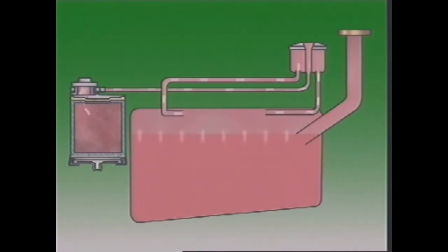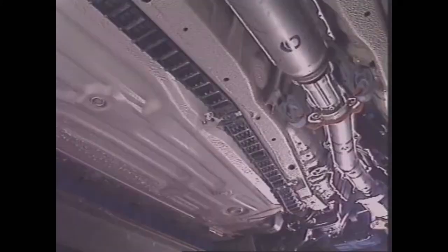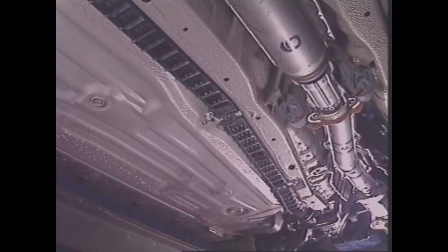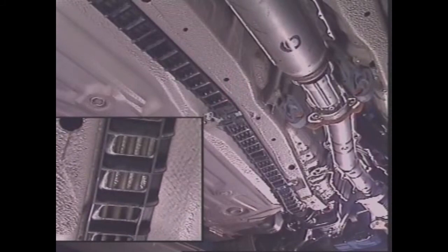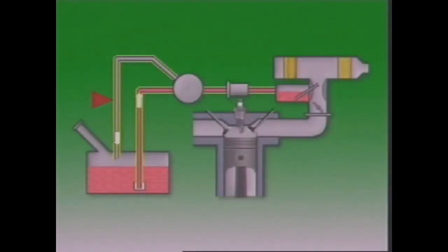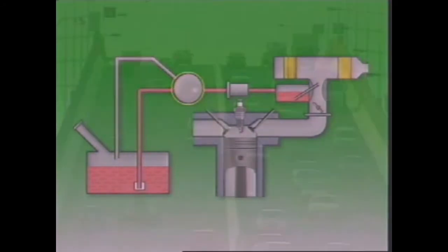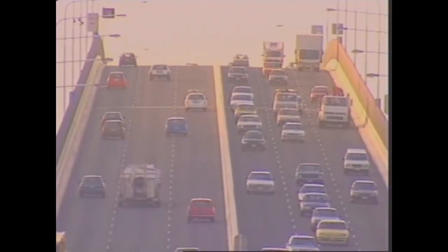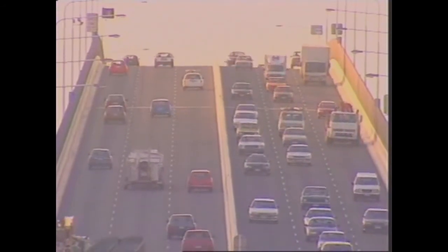This petrol tank has a small separator tank and a number of vents. They're from different parts of the tank, so that for as many vehicle positions as possible, at least one is always above the level of petrol in the tank. Fuel lines are usually made of metal tubing or synthetic materials. A fuel supply line carries fuel from the tank to the engine. A return line may also be provided to allow excess fuel to return to the tank. This helps prevent the formation of vapor that can occur in the fuel supply during hot conditions.